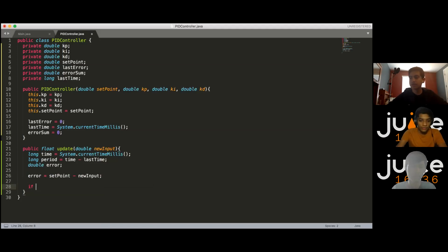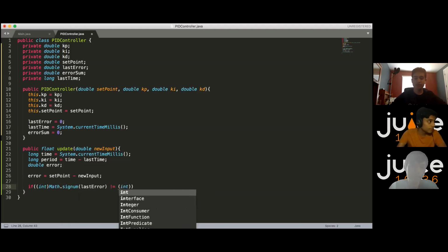When you overshoot your target, the integral portion will slowly start to decrease, but if you don't implement this portion, you'll see that it takes a long time for the integral portion to decrease back down to 0. The best way to solve this is that every time you reach your target, which would be when your error is 0, you should just set the integral portion to 0.